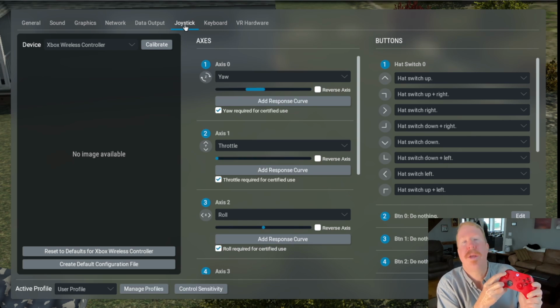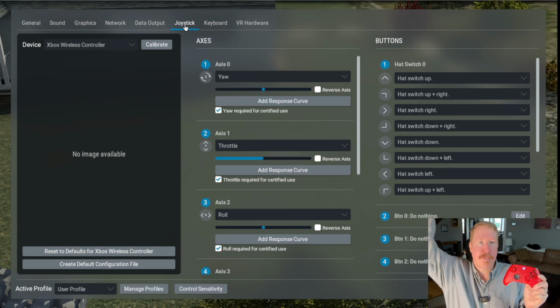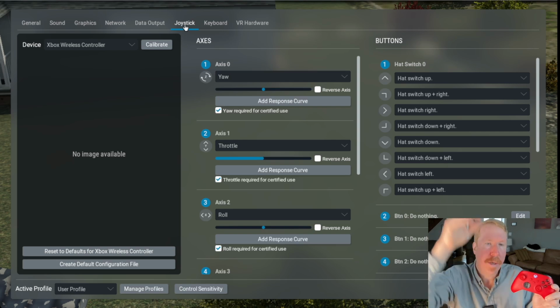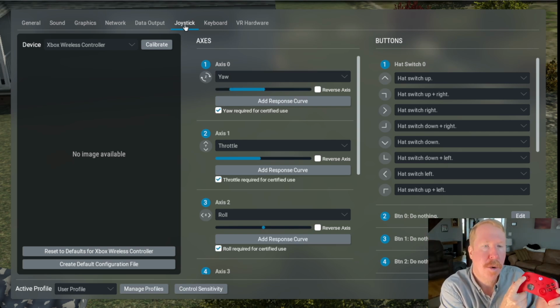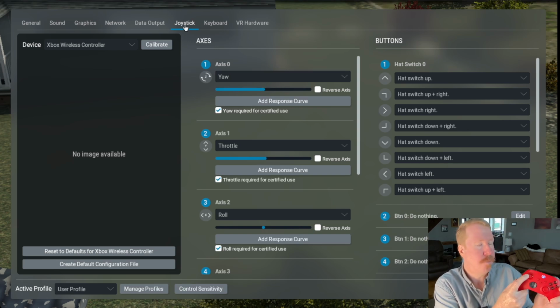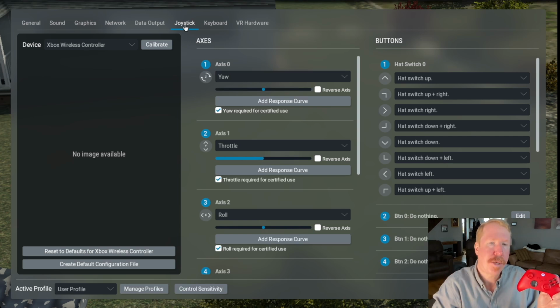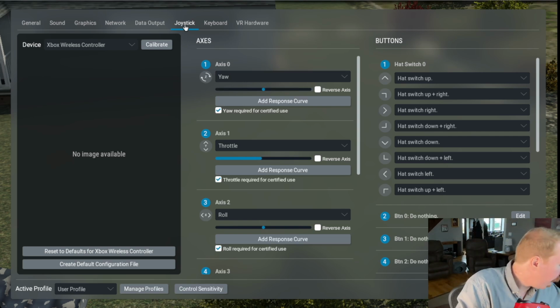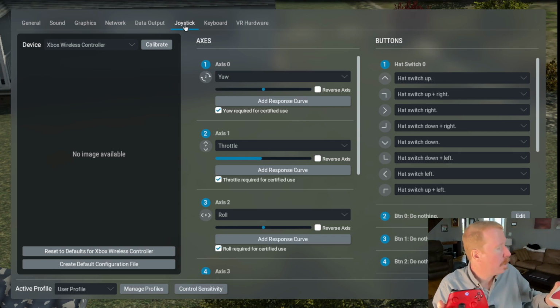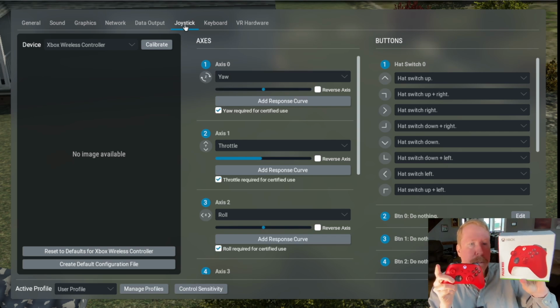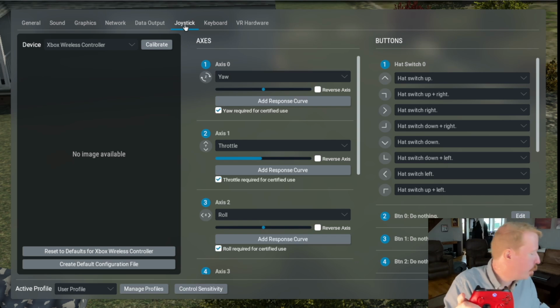And then this, up and down, this is what we're going to call throttle. Why? Push it all the way up, it's just like maximum throttle on my joystick. That's max climb rate. Bring it all the way down, max descent rate. And then finally, as hopefully you can guess, left and right here is just like the rudder. So we have this assigned to the yaw axis. Move this all the way left, you've got maximum rotation rate left. Move this all the way right, you got maximum rotation right. So here, that's how you configure it. Super simple. Configure your Xbox Pulse Red to fly X-Plane, and you're flying just like you would fly the real drone.